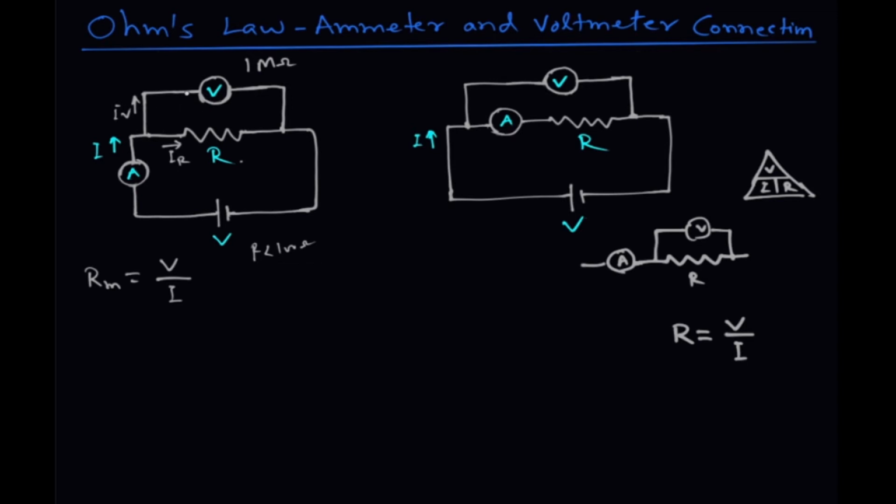Actually voltmeters also take some current, otherwise how would this device operate. So here we can replace this current I by I_V plus I_R.